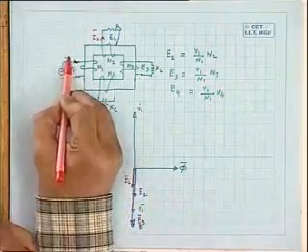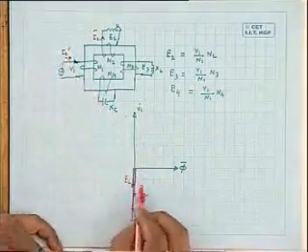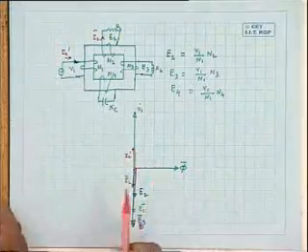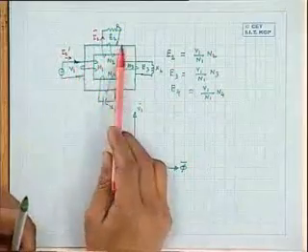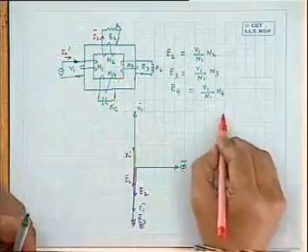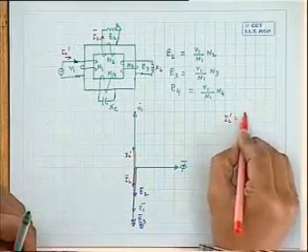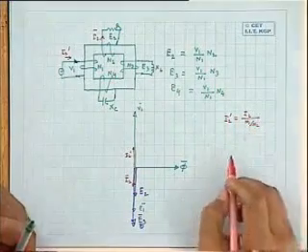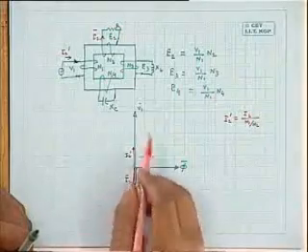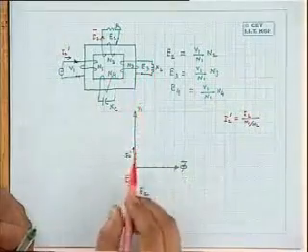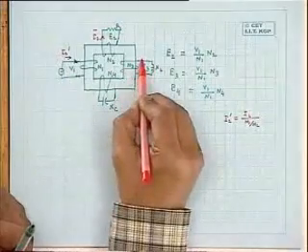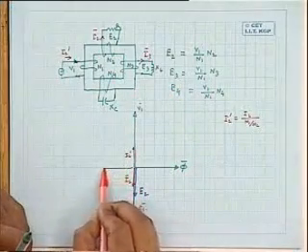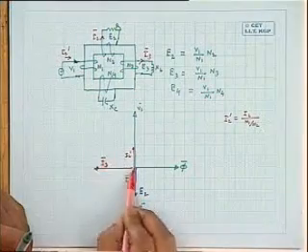Therefore, the moment I2 flows, there appears a current here, I2 dashed, which I will show here. The magnitude of which will be I2 divided by N1 by N2. So I2 dashed will flow. Similarly, if it is an inductive circuit connected across N3, the current in this circuit, if I call it I3 bar, it will be lagging E3 by 90 degrees, the actual secondary current.